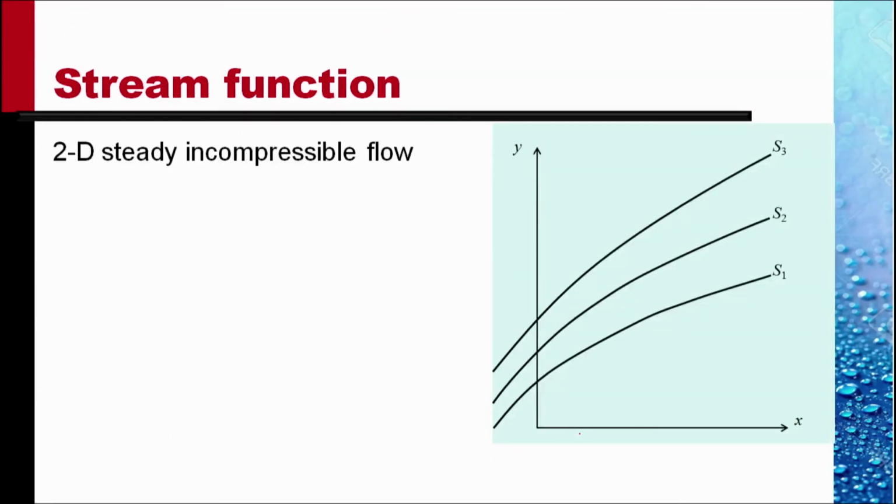Next, talk of another concept, the concept of stream function. A very important concept, a very useful concept. Let us study stream functions for only two-dimensional, steady and incompressible flows, so that the equation of continuity, del Vx by del x plus del Vy by del y is equal to 0, applies.